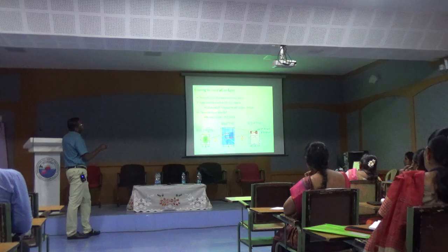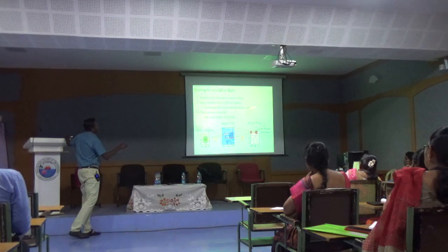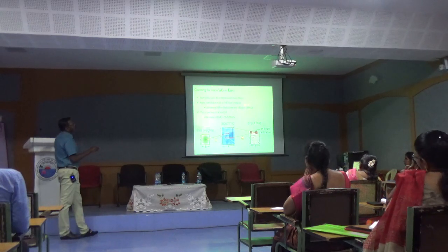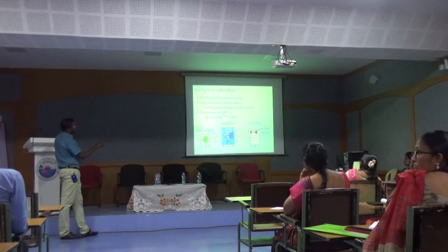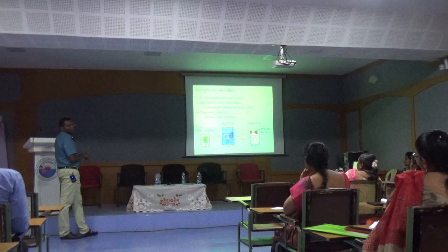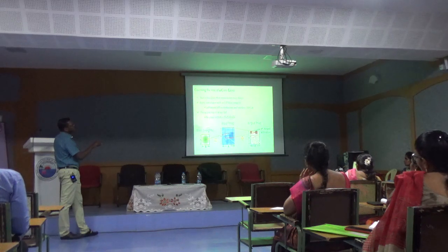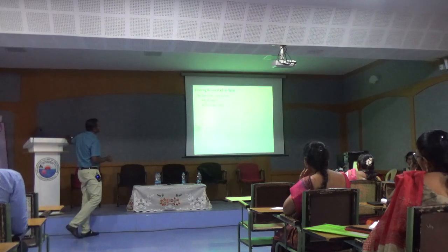So each step is S into R multiplications and additions. So that is a MAC unit. So the output feature map is of size E by F. So a total of S into R into E into F MACs will be there. So this much multiplication and addition will be there. So this is how we calculate the computational complexity.